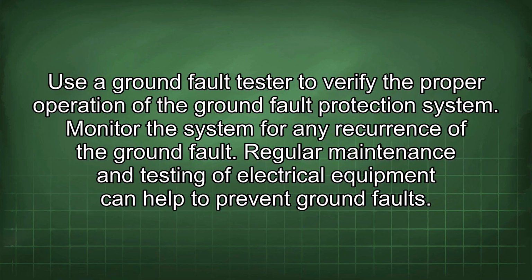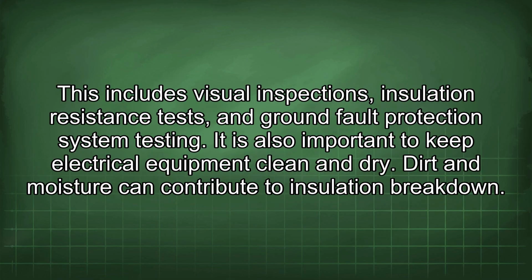Regular maintenance and testing of electrical equipment can help to prevent ground faults. This includes visual inspections, insulation resistance tests, and ground fault protection system testing. It is also important to keep electrical equipment clean and dry. Dirt and moisture can contribute to insulation breakdown.